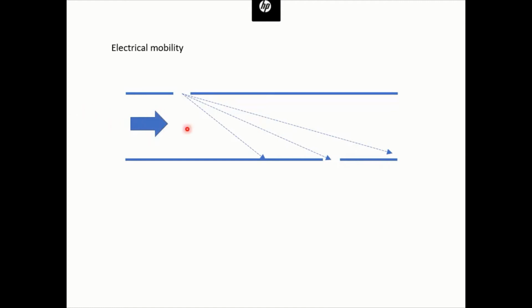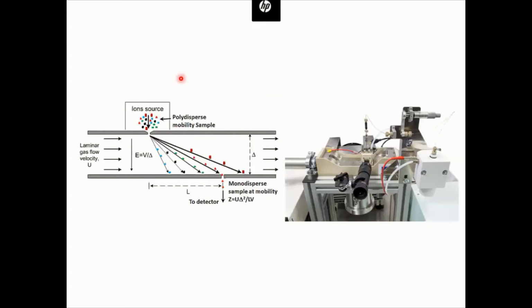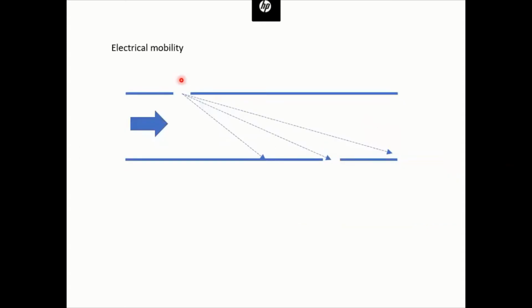So what happens is that this clean air doesn't have any particles in there, right? It's going to establish a velocity field, okay? At the same time, let's introduce the particles that we're interested in, okay? Now we know that because of the drag force, the particles will move with the flow, right? Because there's a relative velocity, there's going to be a drag force. The drag force is going to pull the particles in this direction, okay?